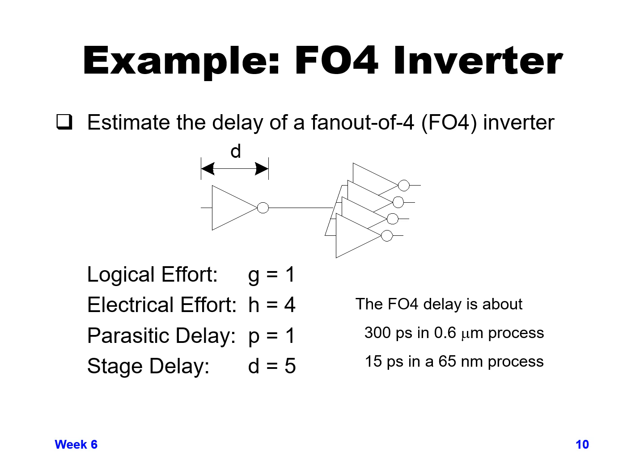So this is an example of how that comes in useful, where you don't need to know what process you're on in order to calculate the delay of one type of gate or one type of stage relative to another. We don't necessarily need to know the absolute delay while we're trying to optimize our logic function.